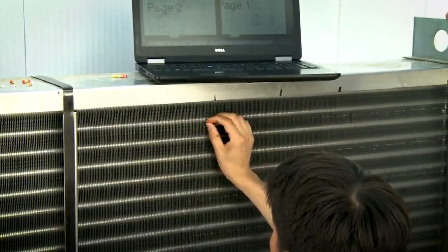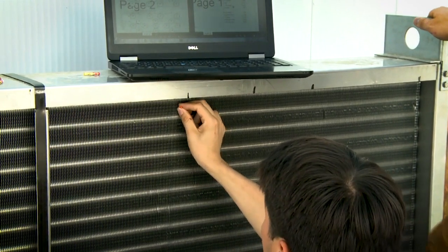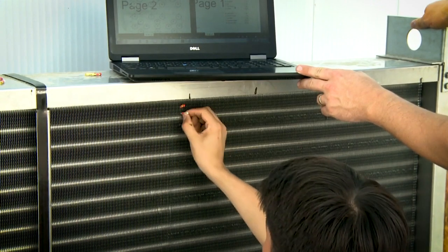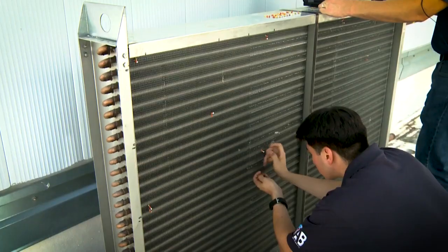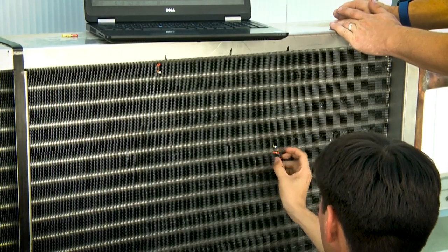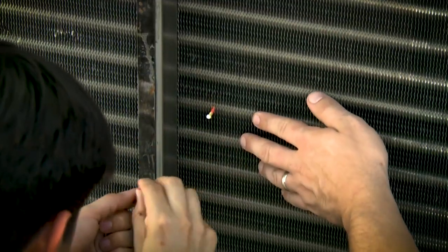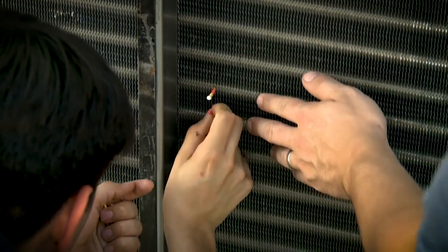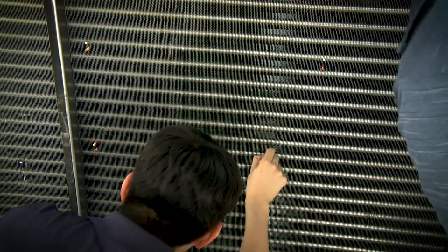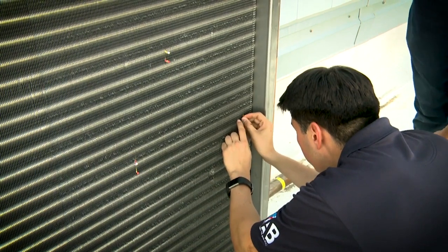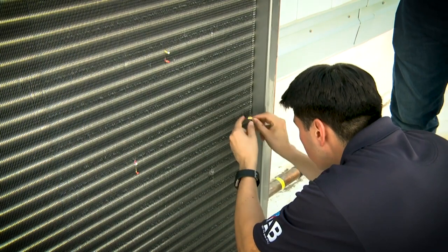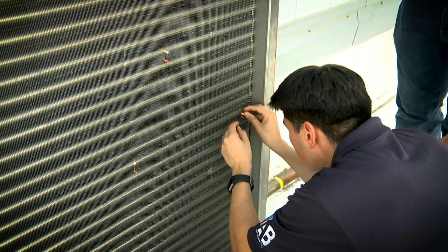After marking the coil's frame with the coil reading dimensions, mark the coil with the intersections for both standard velocity reading locations and offset velocity reading locations. This will map the placement for the center of the vane anemometer for each position point, 1 through 38. In the field, different colored markings can be used directly on the coil to differentiate between the standard and offset velocity reading location intersections. For the purpose of this training video and ease of visibility, colored pens were used to mark the standard and offset location intersections on the demonstration coil.